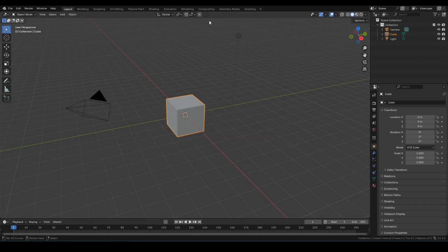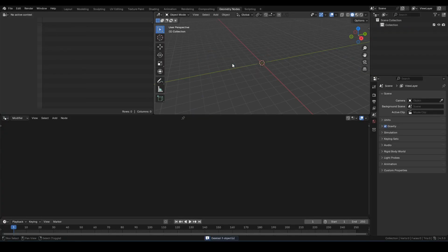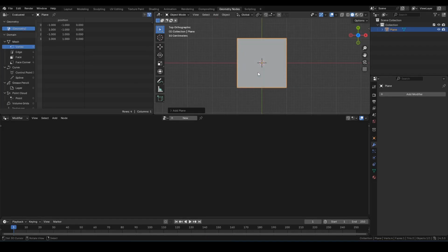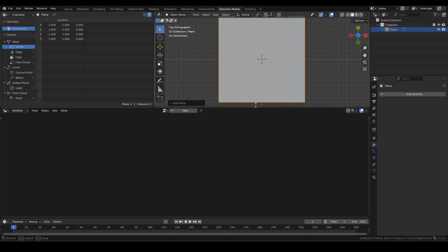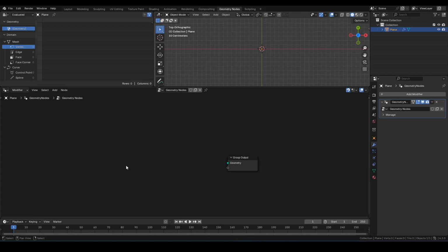Alright, as soon as we get into Blender, we'll hop right into Geometry Nodes Layout. A to select all, X to delete, Shift A, add mesh plane. Using numpad 7 and 5, go into top orthographic view, click on new, delete group input, replace it with string input.